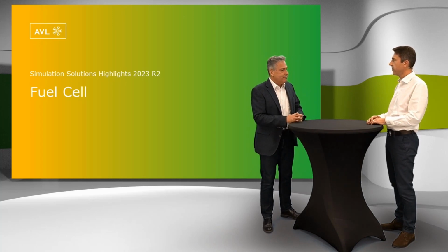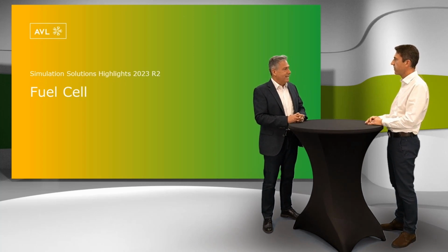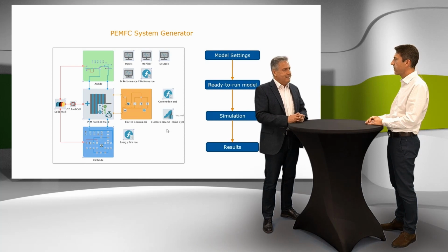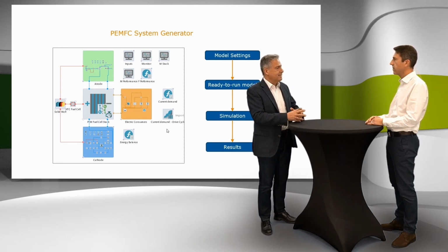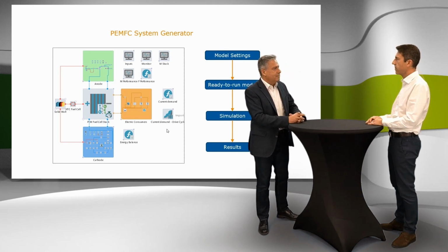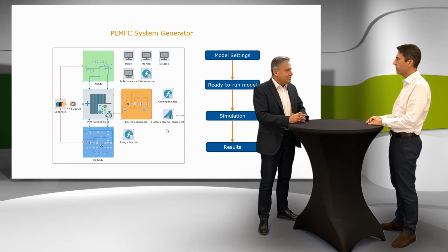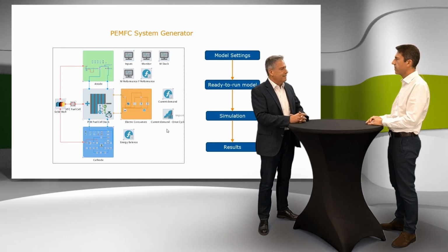And we have greatly enhanced CruiseM in making fuel cell simulation easier for the user, to enhance usability by implementing, as we call it, the PEM fuel cell system generator. That enables the user, with very few input data, so the cell active area and the number of cells in the stack, to automatically build up a complete PEM fuel cell system comprising the anode and the cathode media supply, comprising the electrical auxiliaries and the load.